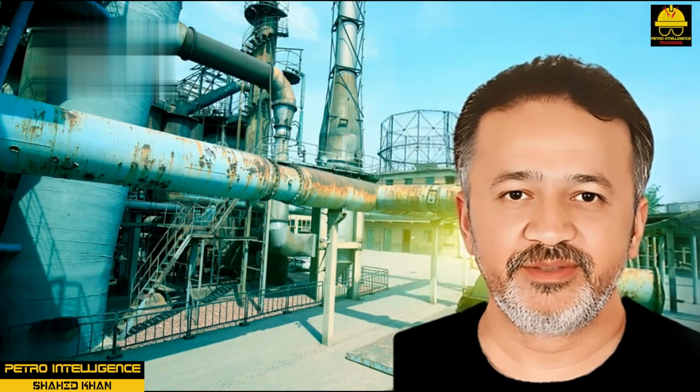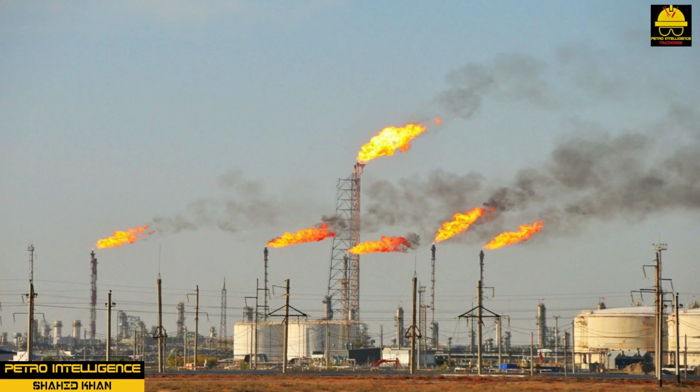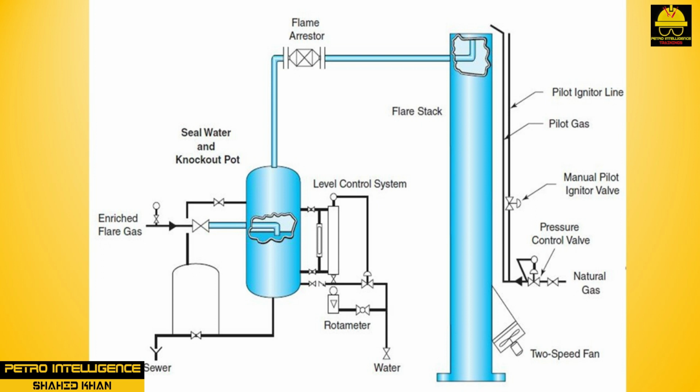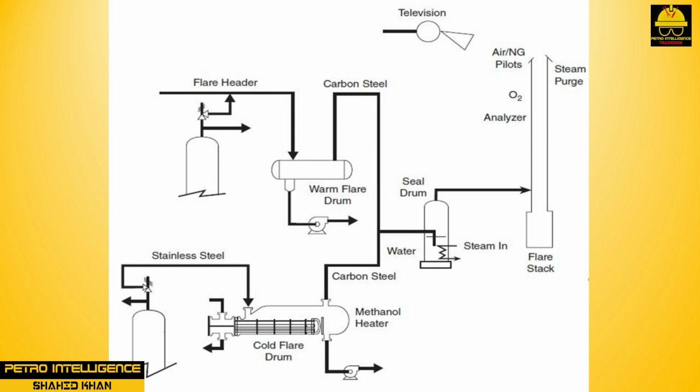Relief and flare systems. Flare systems are used to safely remove excess hydrocarbons from a variety of plant processes. Flare systems are composed of a complex network of pipes and headers connecting to a knockout drum and flare. Governmental laws and regulations require the flare to be located a safe distance from the operating units and populated areas. Flare systems are part of a plant's safety system. Most process units are lined up to safety relief valves that lift when specified pressures are exceeded. These safety valves discharge into the flare header. Unexpected process upsets are dumped to the flare system as a last course of action.